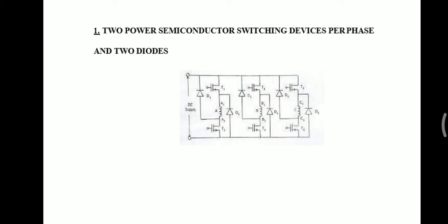The current in the phase winding is the result of the logical AND of the rotor position sensor and the chopping frequency. As a result, it is possible to vary the effective phase current from a very low value to a high value by the following methods. By varying the duty cycle, we can control it. By varying the conduction angle also, we can control it.